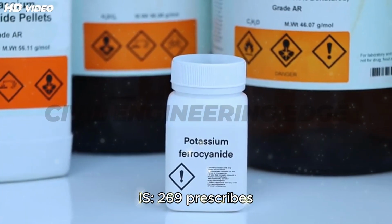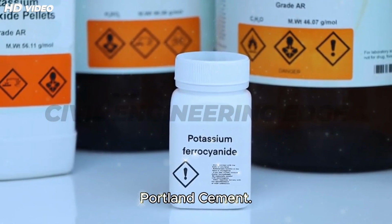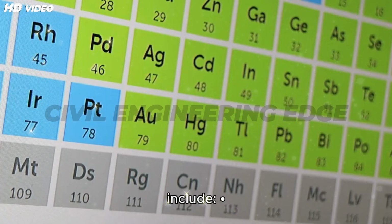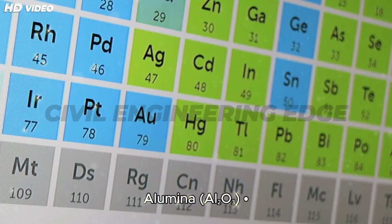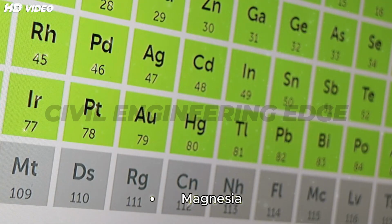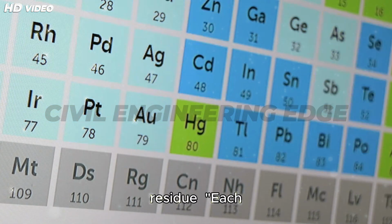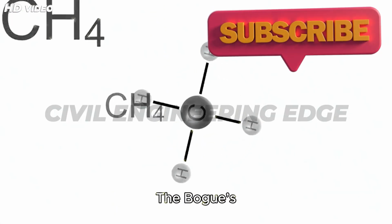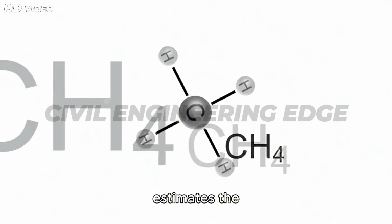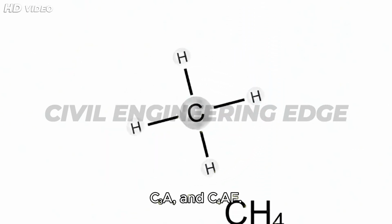Chemical composition. IS 269 prescribes limits for the chemical constituents of ordinary Portland cement. The key components include lime CaO, silica SiO2, alumina Al2O3, iron oxide Fe2O3, magnesium oxide, sulfur trioxide, loss on ignition LOI, insoluble residue. Each compound has a role in the behavior of cement.